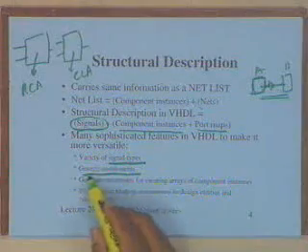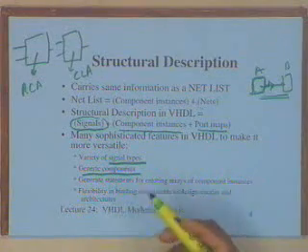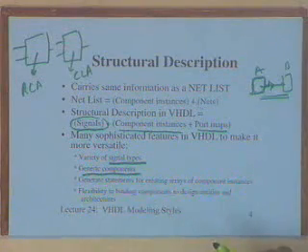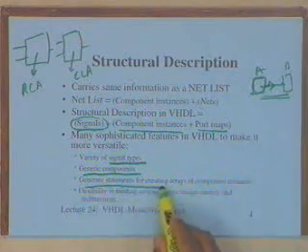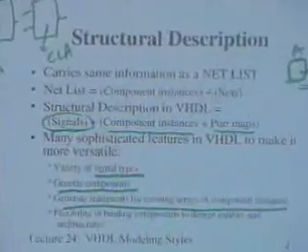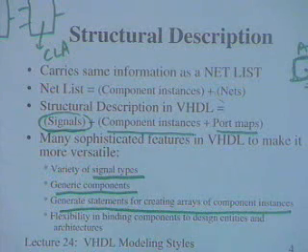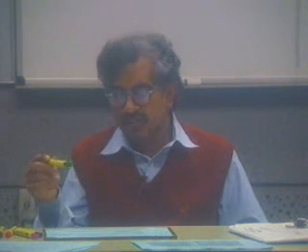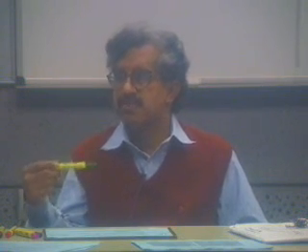So generic components are used, of course, a major use being the sizes of components that you can define, but other parameters can also be generic. When you want to create multiple components, which is typically the case for iterative circuits, you can use what are called generate statements. The generate statements can primarily instantiate a number of components of the same type. You only want, for example, the array number to be different. Say you want to create an 11-bit adder. One way to do it is to have 11 instantiations specified, or you use a generate statement. Again, we will see examples of that.